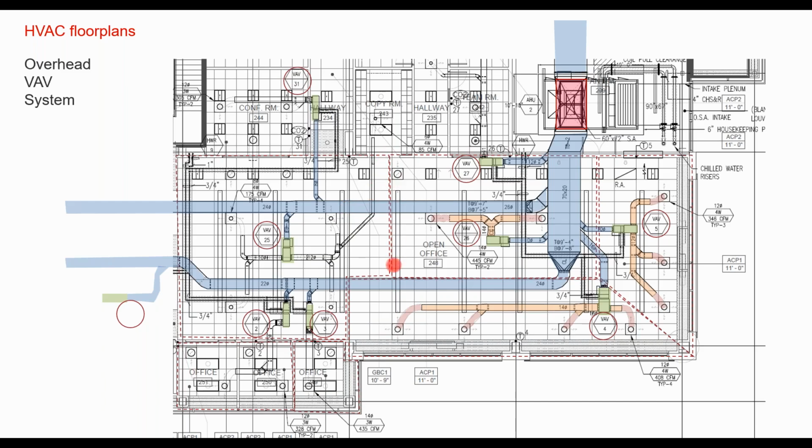And in the background, you can see we're overlaying a little bit. It's that same zone that we were talking about before, the same system that's got this big perimeter zone, where you can see the thermal zoning is set out against this envelope. And you'll see that there are thermostats shown here as well. So you might be looking for which VAV boxes are on which thermostats. That might help you dictate which VAV boxes should be on the same zone, for example.